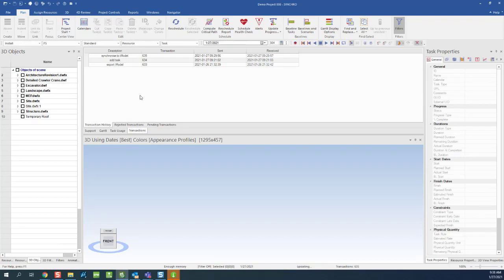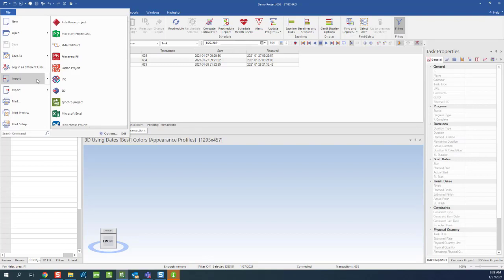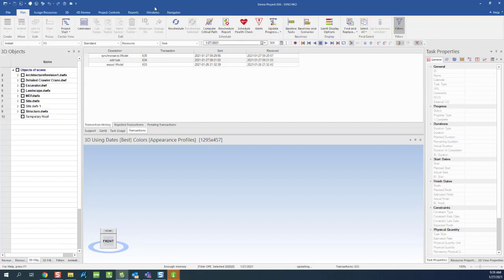So I would say typically you would want to try both methods when you're starting out in a project. You want to see what your file size is, what your workflow is going to be, because in SYNCHRO Pro right now, one limitation I know is that we can import a SketchUp model in SYNCHRO Pro directly, but we don't have an iModel bridge for SketchUp yet. There are workarounds by converting SketchUp to a different format, for which we do have an iModel bridge. So those kinds of limitations need to be considered.